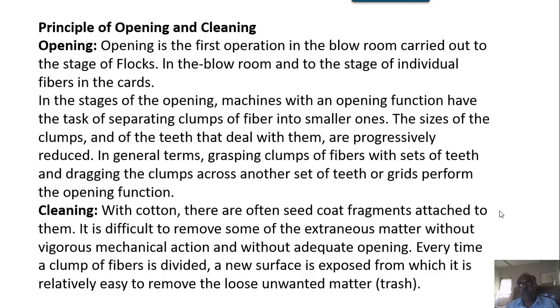So the primary objective here is to separate out the extraneous matter which is undesirable, in the sense that it is not required in the spinning process and is not to be spun into the yarn. And secondly, the tufts, the clumps, should be in such an open state that carding does its job very comfortably. So this is the objective.